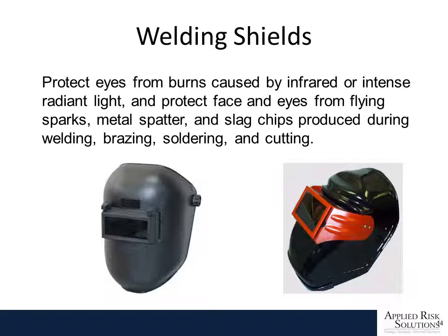Welding shields provide adequate protection for welders, but other workers in the area working around welding must also be protected. For people that are not actually welding but working in the area where there's welding, we must provide shields to protect them from the radiation and the light.